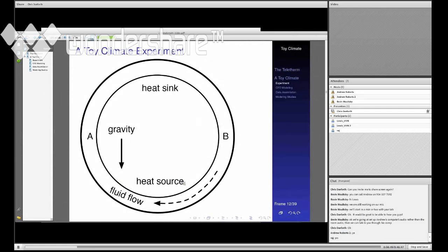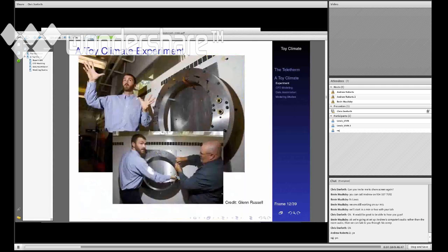And what we do is we apply a heat source along the bottom half of the loop on the outside, either with a bath or heating tape wrapped around it. And then a heat sink, so some sort of cool, you can use just room temperature air with a fan blowing on it, or you can actually have a cold bath on the top half. And the system, if you create a small temperature difference between the bottom half outside and the top half, and there's water on the inside, since it's oriented vertically, let me show you a picture of what it looks like. So here's a closed off one, and me standing in front of it, and these are little temperature thermocouples that we use to measure what's going on inside of it. So that's what it looks like.